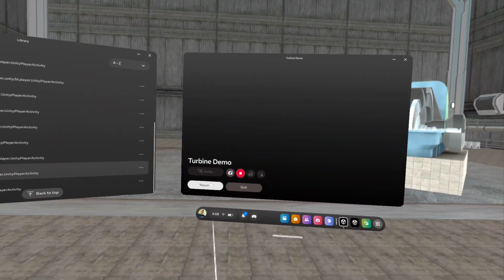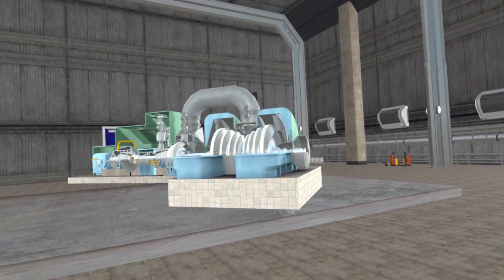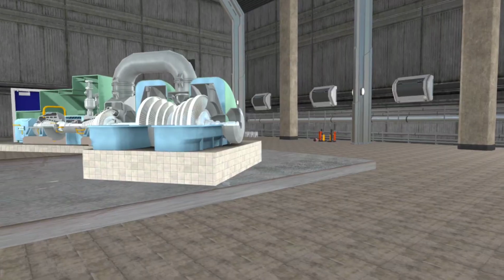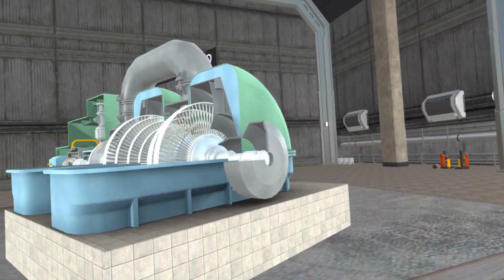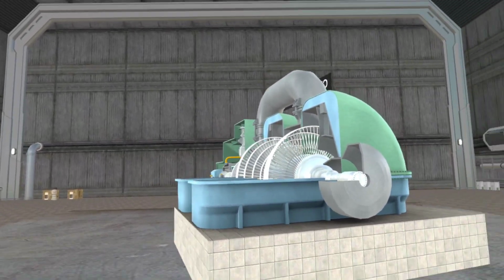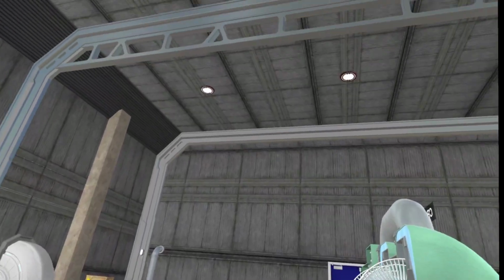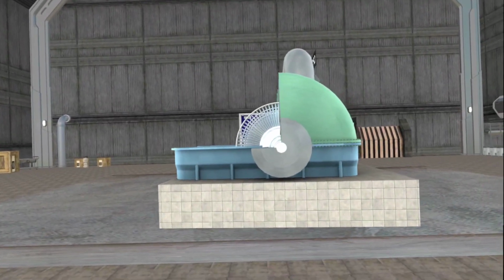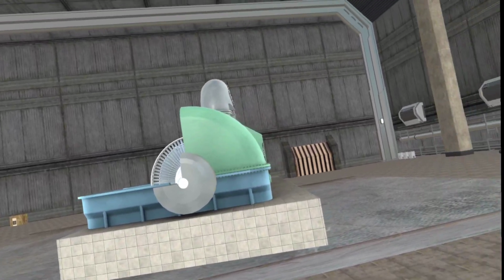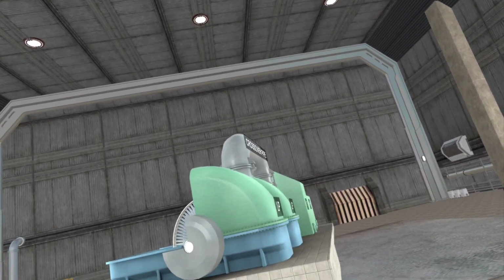the expansion of the steam to improve its thermodynamic efficiency. When the high-energy steam passes through a series of rotor blades, the pressure difference across the blades induces a resultant force in an upwards direction, thus making the blade rotate. Steam turbines are widely used in power generation industries.